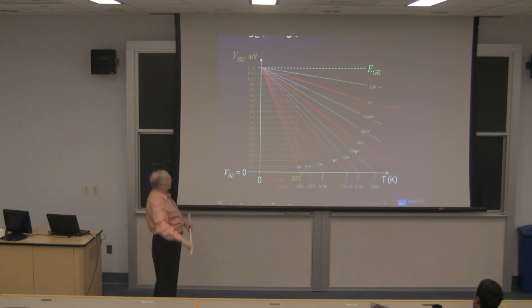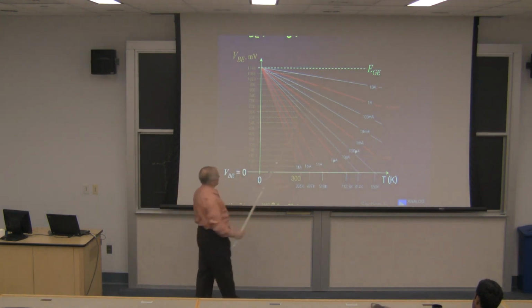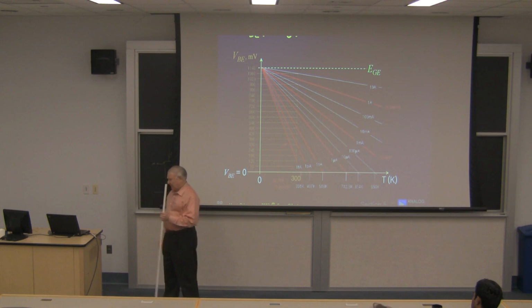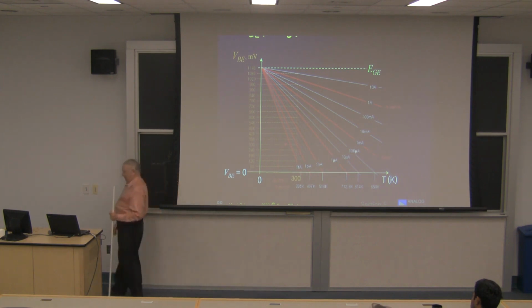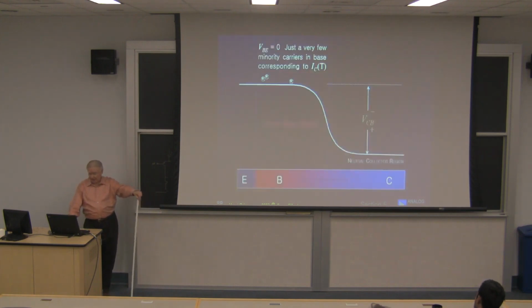Anyway, so the question is, could you make a device such that the slope is so low that it's constant with temperature? Well, you can't, because you can see how big those current densities have to be. But you can easily add a PTAT voltage to any one of these lines, and that's something of a bandgap, which is a separate topic.